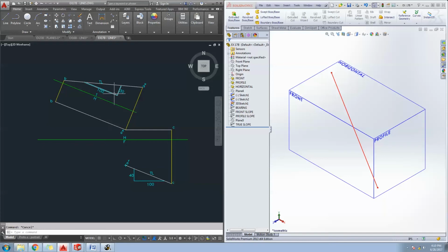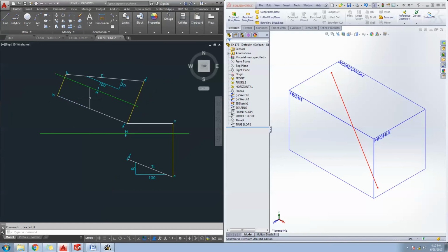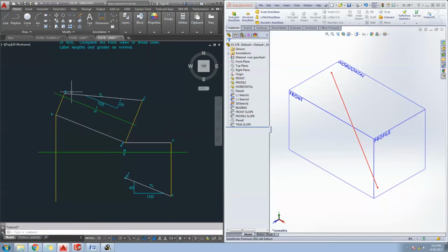And now we're ready to project from auxiliary view 1, which that superscript should read 1, down into the frontal plane. So now we'll take the, okay, we're in the construction layer, that's fine. Straight down like so.